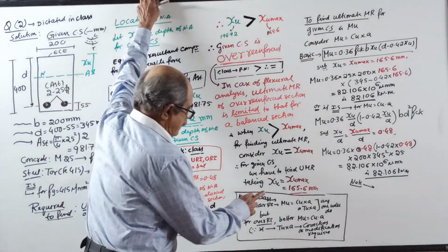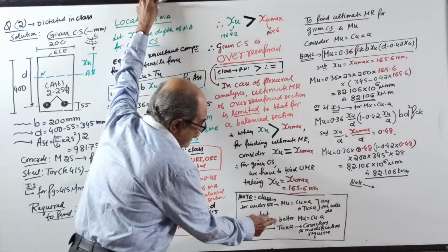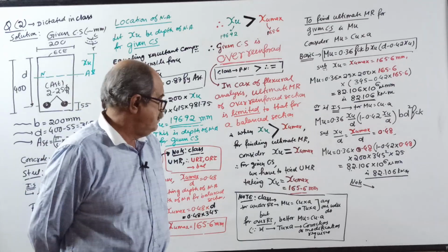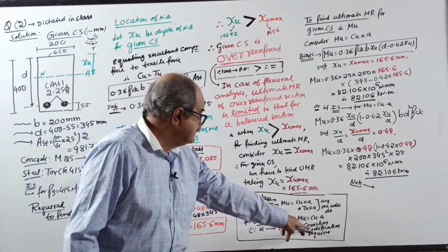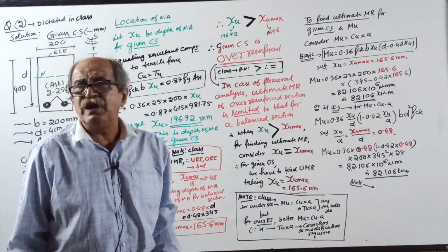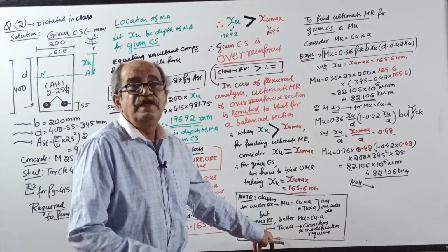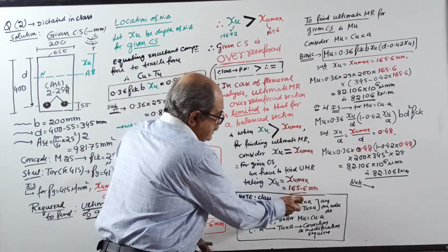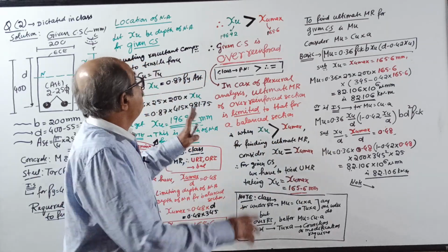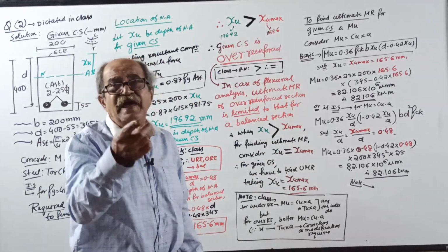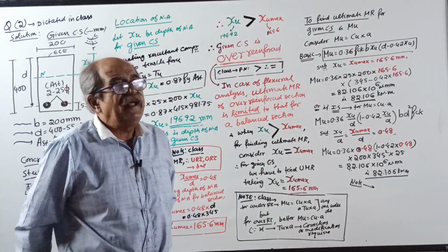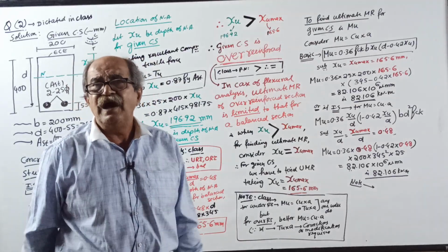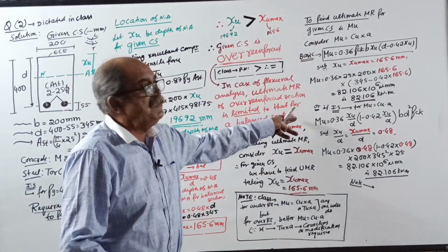Okay, over. But remember, for the over reinforced section, it is better to use MU equal to CU into A, because if you take TU into A, some corrections or modifications are required. Therefore, in the class, he is going to solve and find MU using CU into A only. After the question is completely over, you write there what happens if you use TU into A, or what modifications are required. I will tell you in the class, but let the question be first over.